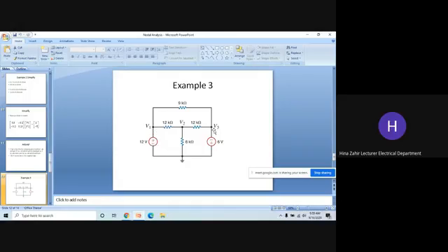But we cannot say V3 is 6 volt. No, V3 cannot be 6 volt. V3 is minus 6 volt. Because if minus to plus is plus, then plus to minus would be minus. We cannot give them the same sign. We already have these voltages.